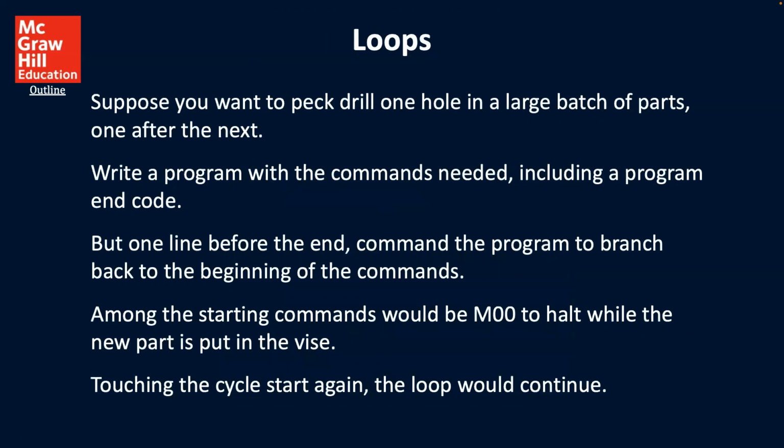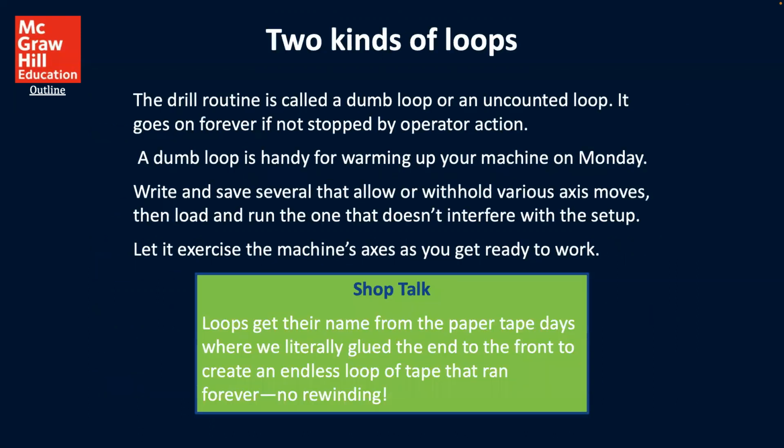So for loops, suppose you want to drill one hole in a large batch of parts, one after the next. Write a program with the commands needed, including a program end code. But one line before the end, command the program to branch back to the beginning of the commands. Among the starting commands would be M00 to halt while the new part is put into the vise. Touching cycle start again, the loop would continue. So here we're seeing this type of looping behavior that we would like to have.